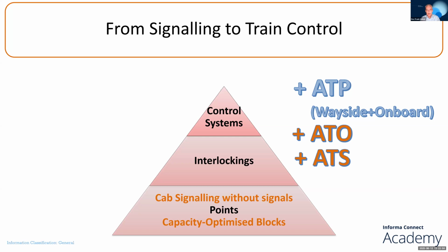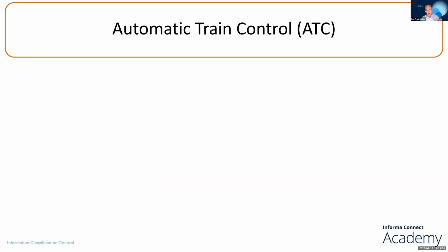And what you can also have in modern train control, you see I have replaced the block sections with something better, with block sections that are optimized for higher capacity, which mostly means they will be shorter, quite a bit shorter, in fact. So this whole thing, everything that you see on this slide here, is what I call modern train control. And I said sometimes this is called digital signaling, sometimes this is called high capacity signaling, sometimes this is called high performance signaling. That's a term that I came up with, which I think fits better than high capacity. And another term for that is automatic train control. So that's a description of everything that you have seen on the last slide.